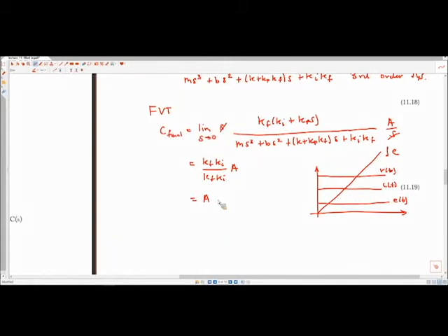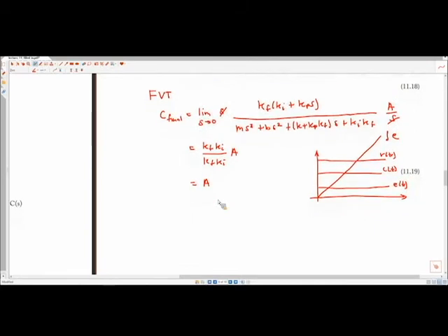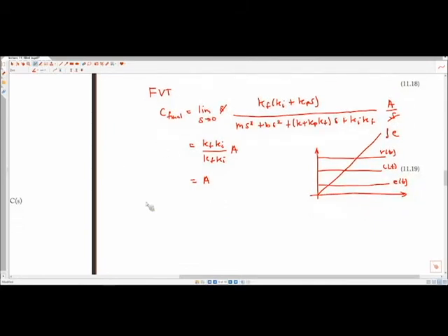All right, so now this is steady state. It doesn't say how long it takes you to get there, but it tells you that the system will eventually get to the value you want it to get to. Okay, so some general rules. If I increase KI, C final will go to A. Good.